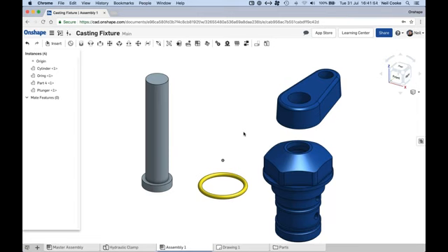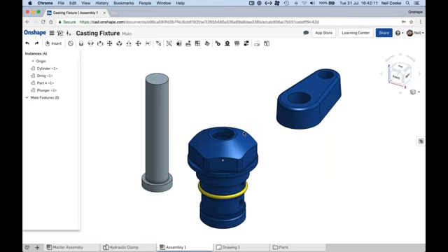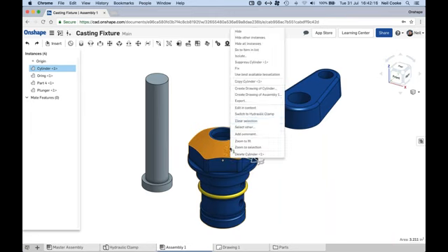So in order to get this moving, and this is one of the reasons you create an assembly, to look at motion, to create an accurate bill of materials, but sometimes there's no need to actually create an assembly. You can just create the data in a part studio. Okay, but what we'll do here is we'll take this part, I should say, right click and fix it.